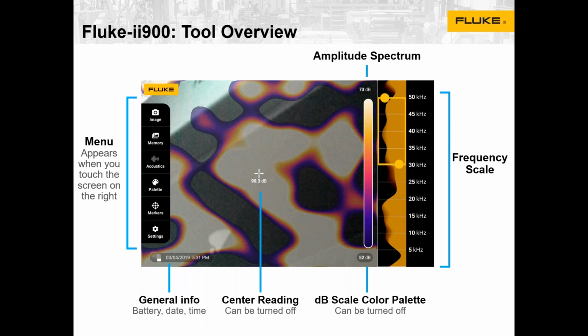So that's particularly useful in really loud or noisy environments where you've got a lot of rotating equipment, or you've got a lot of processes happening around you that emit a lot of noise. You can adjust the frequency range to eliminate all of that noise and really hone in on the specific area where you would find a compressed air, gas, or vacuum leak. So that's the tool and how it's used.